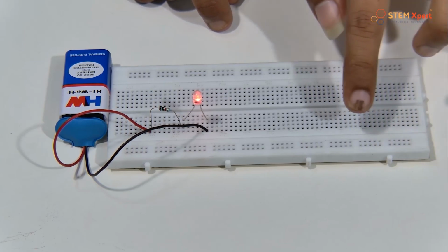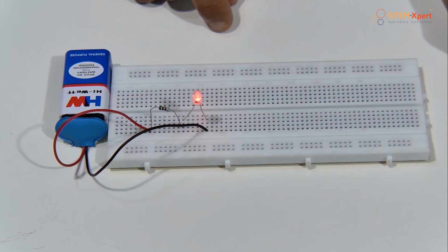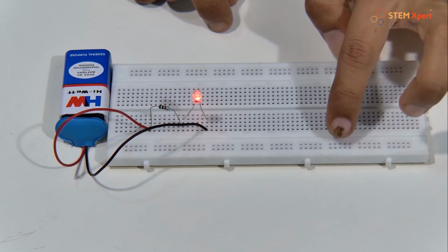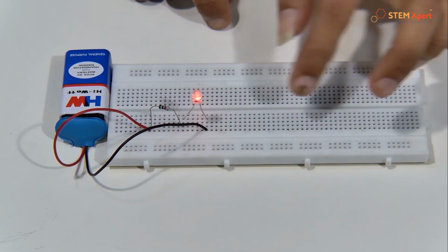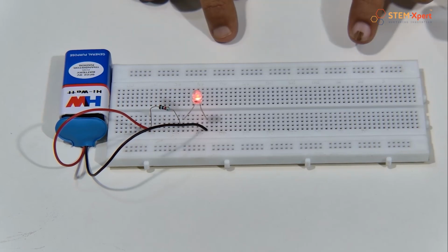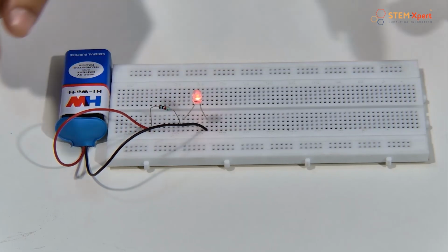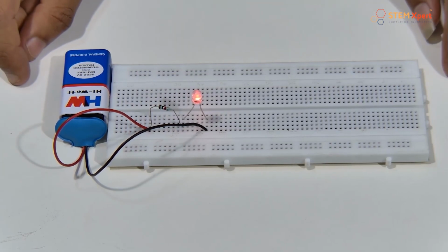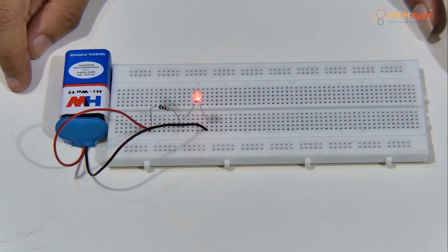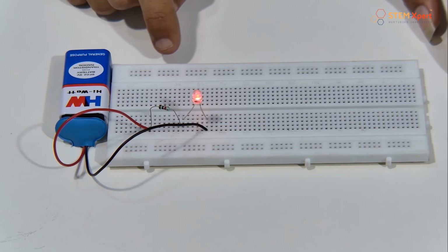So remember one thing: in a larger breadboard like this, the connection only goes up to 5 points in the A part and D part. So remember 1, 2, 3, 4, 5. At the 6th section, the connection will not be there. It means that it is not interconnected with the 5th point shown in our A part. I hope you have understood about the breadboard. For beginners like you, a breadboard is a solderless board that can be used to build and test circuits. I hope you have understood each and every component to build our LED lighting circuit and the concepts regarding the LED, resistor, battery and breadboard.